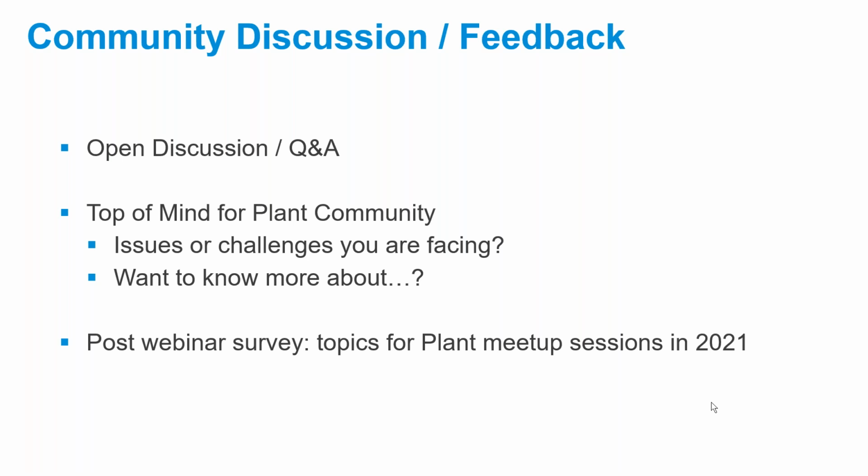But with a SQLite project, the first one in locks the database, and the next person in can get access to the files, but they may not be saving back the data or creating drawings. They think they're creating them, but it's not storing it in the drawing registry in the project, in the piping database. So we definitely discourage people from using SQLite for a multi-user environment. If it's just one user in a SQLite environment and you're still having disconnects, all I can think of there is maybe a permissions or network issue if you're on the network.